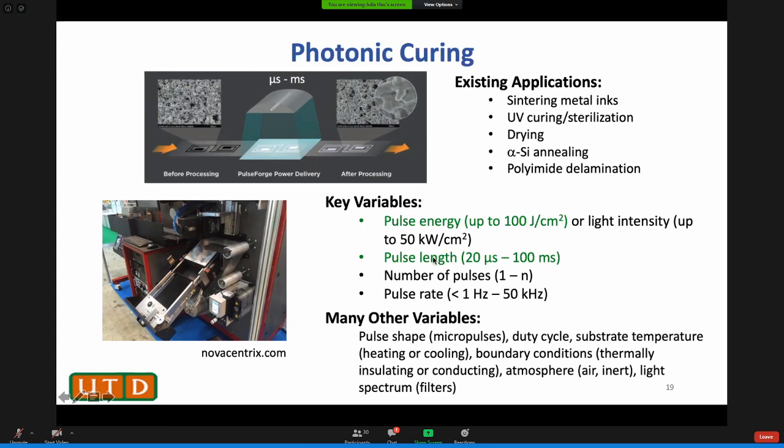At the end, the substrates get to different temperatures because their specific heats are different. Nonetheless, all of them are well below 100 C. So the substrate does not heat up in this technique. As I show you, the film surface can reach high temperature with minimal substrate heating.